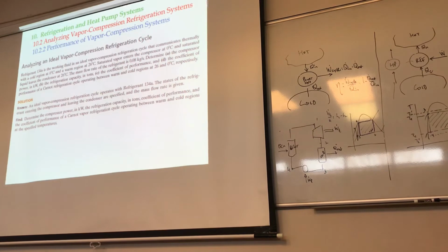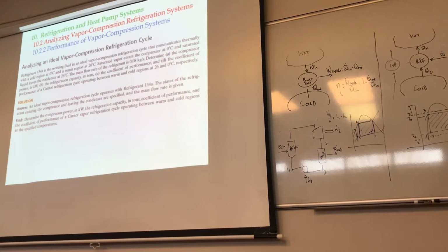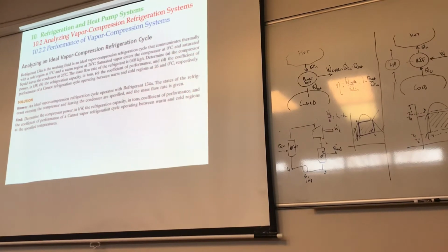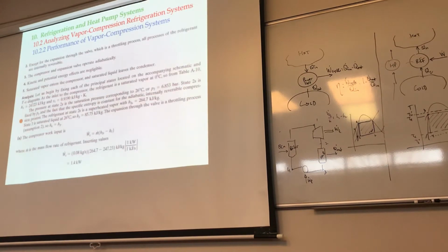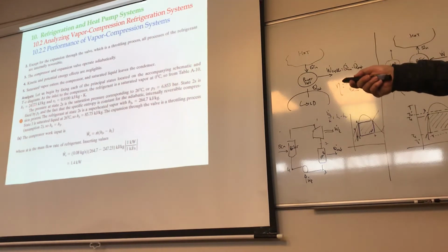Now, before I move to the next section, what else should I read? The S. The S, because it's the isentropic process, right? And the value of S should be 0.919. Okay, you guys are rocking, good. Let's see. So, it's really what it is. See, 247.23 and 0.919 for state number 1.